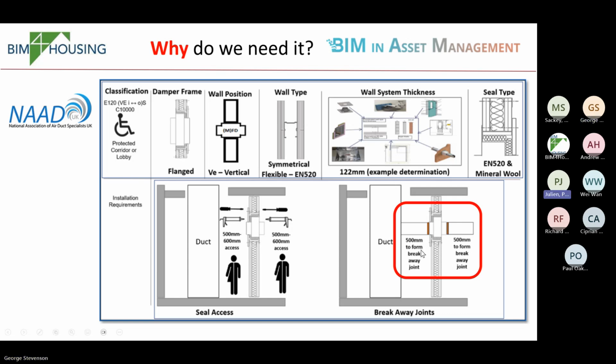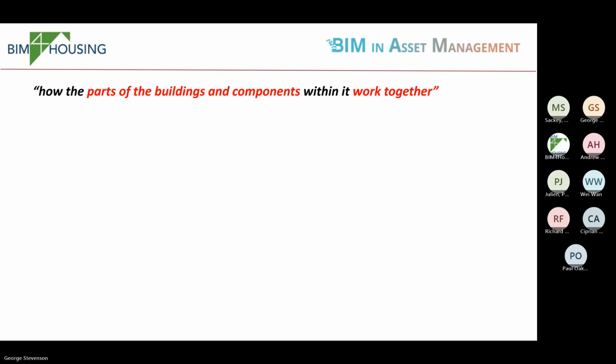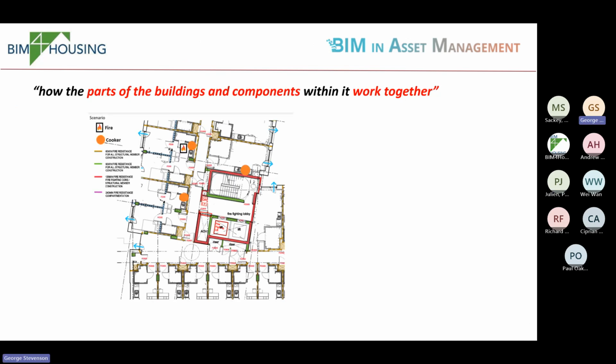Now, in many cases, as I understand it, the information that you get doesn't even tell you where the dampers are. Yes. So what we're trying to do is make it so that we can heighten people's awareness. So we can run scenarios to say, okay, if fire breaks out in the kitchen, we need to prevent smoke from getting into that lobby area there, the stairs.